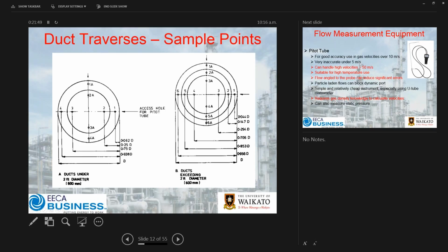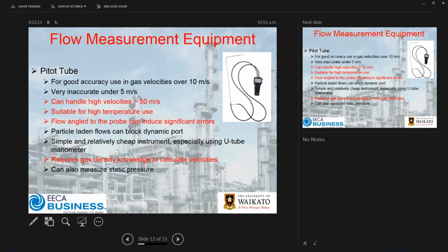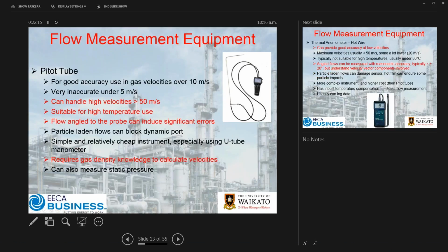and you'll get a measurement across those multiple points, and typically the annubar is an aggregator of those, and then you'll get a pressure differential which corresponds to a velocity, which based on your duct dynamics, a volume flow rate. Now, if you're going to be really careful, you'll then also look to do a temperature or density correction on that data.